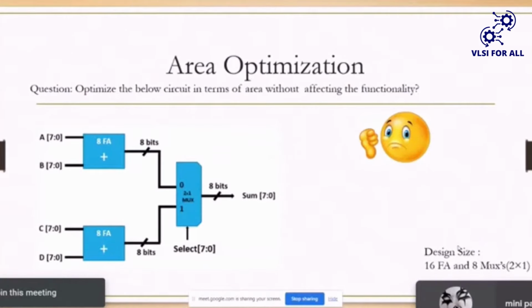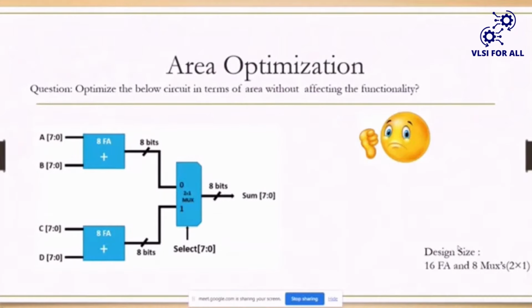Means to obtain that function, you require two NOT gates to get A bar and B bar. And you need two AND gates to multiply A bar B and A B bar. Finally, you require one more OR gate which represents A bar B plus A B bar. So what I am telling you is, as XOR gate internal logic is more, the power dissipation is more in XOR gate because the logic is more.